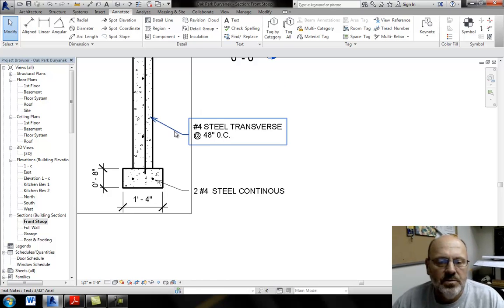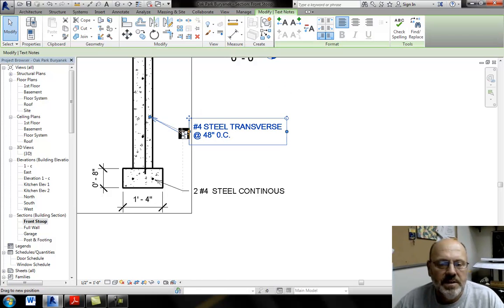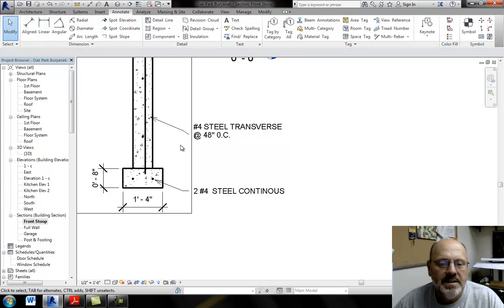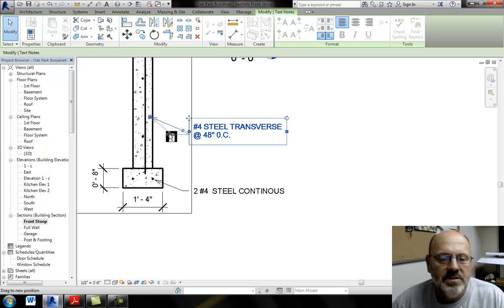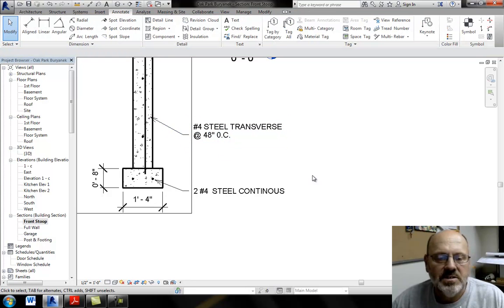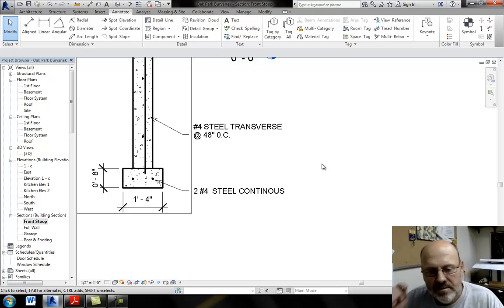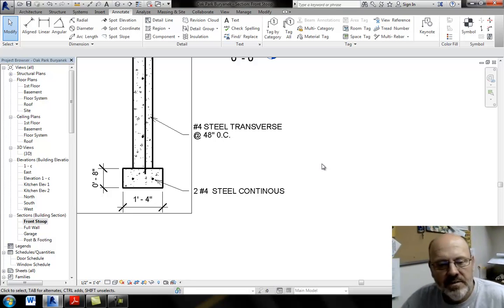And these little shoulders, people start moving these around and things happen like that. Those shoulders need to be flat, and they shouldn't be really long here and really short here. We need to keep that about the same length. So that's just part of what you look at in neatness on the drawing file.